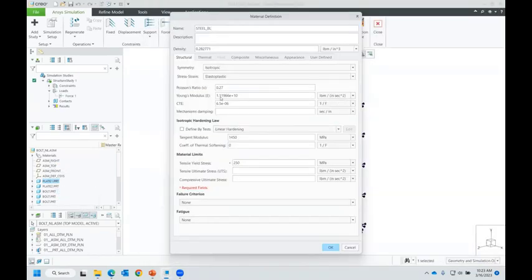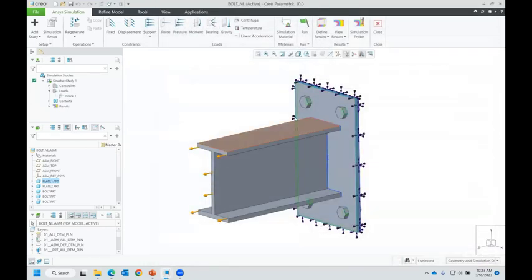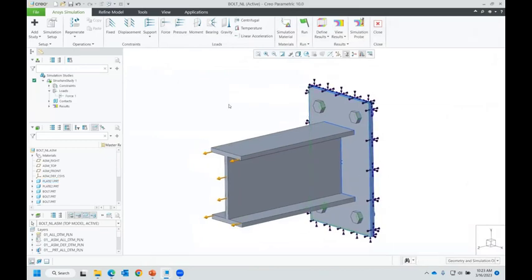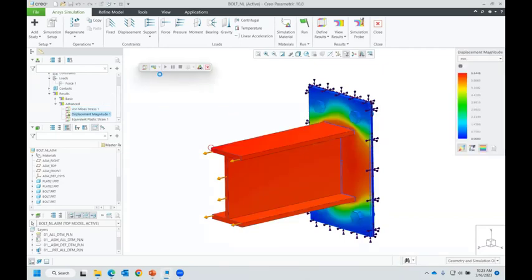we go to properties, you can see I have the linear hardening defined. Okay. You also have to have a tangent modulus assigned. So those 2 things, I'm sorry, and also the tensile yield stress. So you change it to linear modeling, add a tangent modulus and a yield stress, and then the solver recognizes that that's a material that it wants to use bilinear plasticity when it runs. Okay, so same contacts, and I look at results. Let's just look at von Mises. And of course, you should always look at the deformation first.